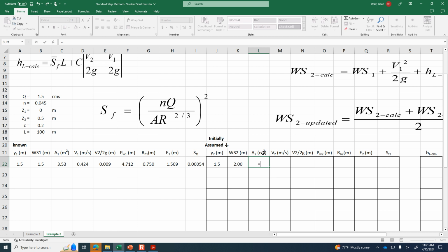And that is for one of the sides. And of course, the wetted perimeter includes both of them. So the total wetted perimeter would be that times 2. So that's this, and there's 1 on either side. Okay, so the area, what we're going to use for the wetted perimeter is just the depth squared. Area is depth squared, so depth to the power of 2.